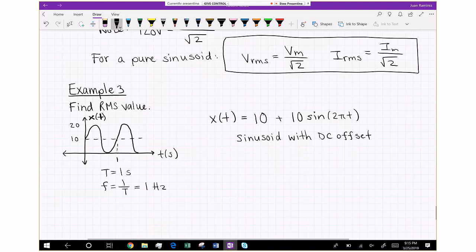So we'll intentionally add an offset and scale it so that our measurement system could read it. And then once we do any type of signal filtering, conditioning, that signal will go into an analog to digital converter typically, and the output of that analog to digital converter will go to a microcontroller. And in the microcontroller code, you will account for that offset and the scaling. That's a typical technique we use.